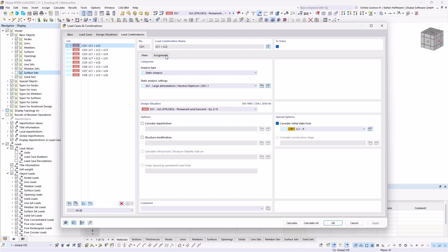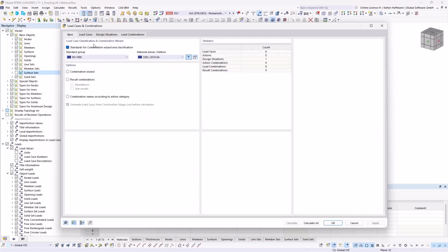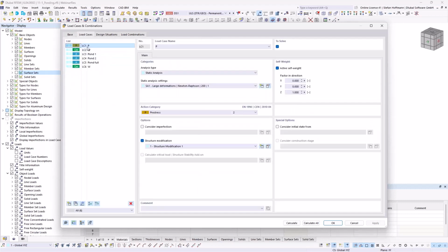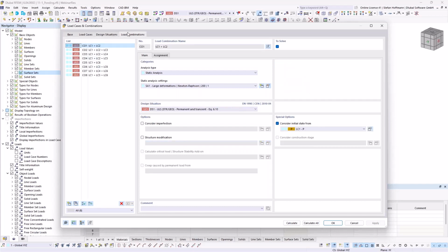So for my example, in the first case, I want to pre-stress my membrane. Also, as you can see in the load case with the activated dead load material, and I did deactivate my rigid members because the shape should be found, and I expect that the membrane will not lay down on the members without these links, and later I will use these links.